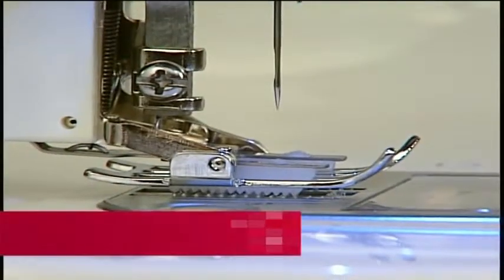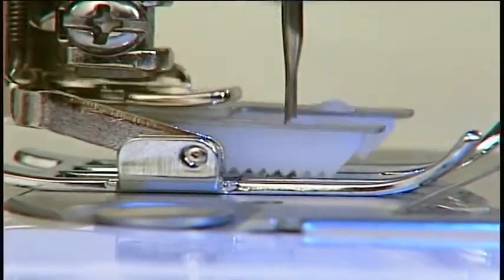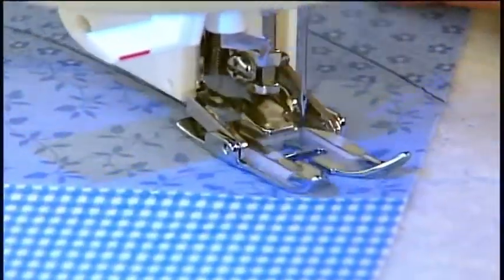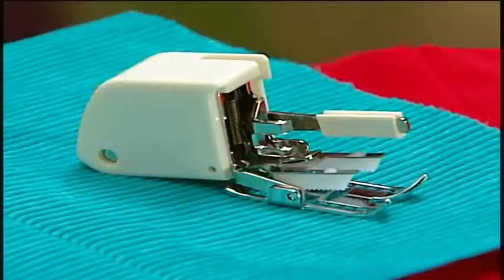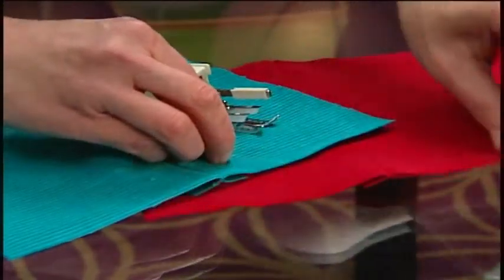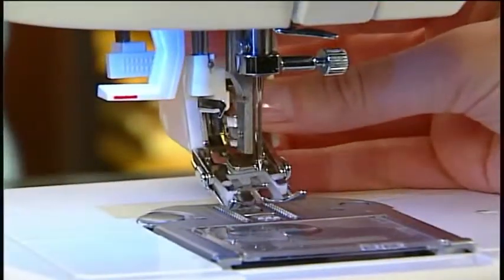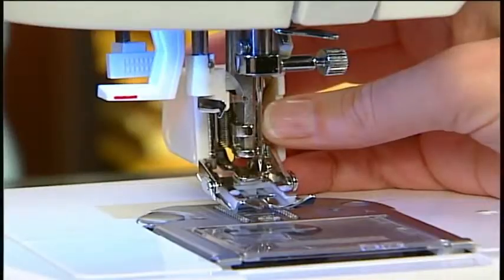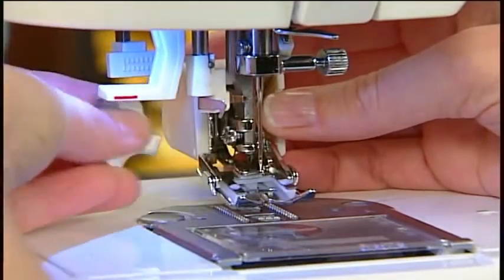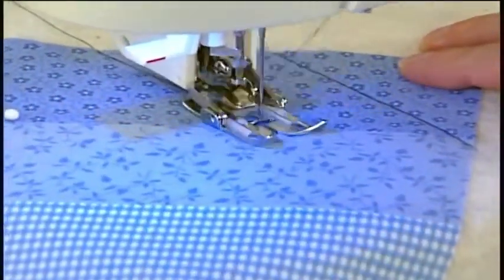The even feed foot is sometimes called the walking foot or dual feed foot. It works just like another set of feed dogs, helping to feed fabric through the stitching area. Use this foot to prevent shifting of quilt layers or shifting of seams in fabrics like velvet or corduroy. Remove the regular foot and shank. The even feed foot is then placed so that its arm is resting on the needle bar. Once it is in position, tighten the side screw. Secure the materials together, then sew.